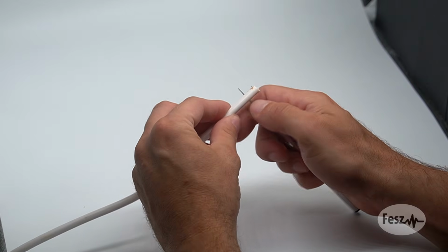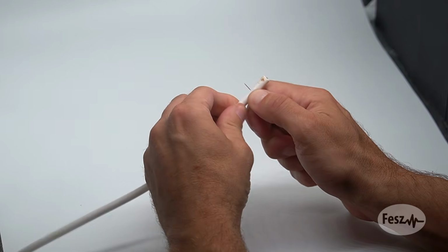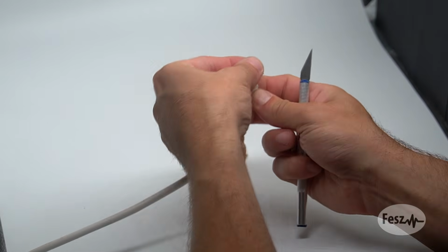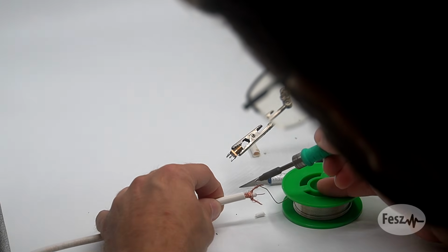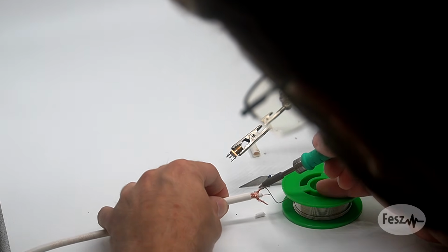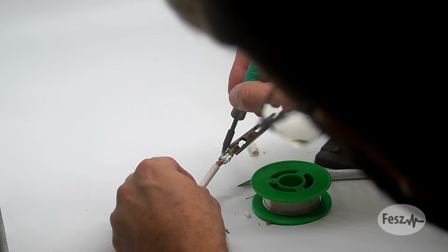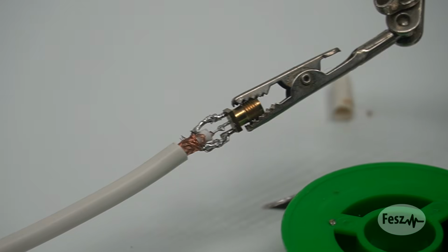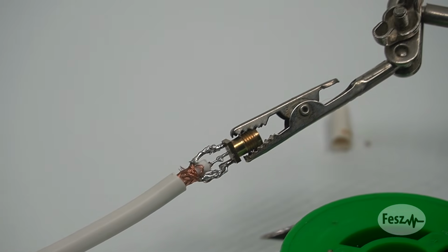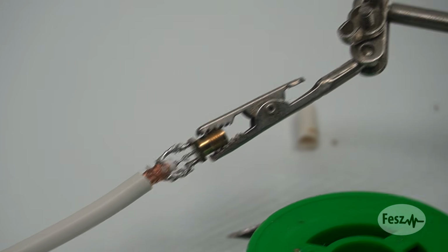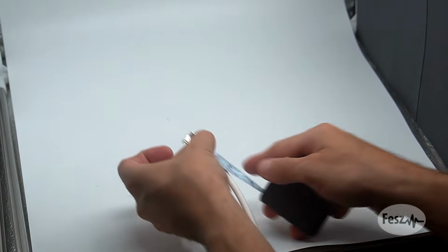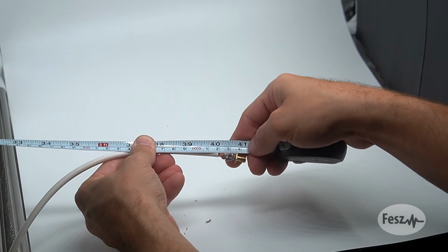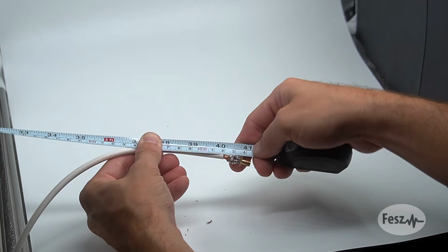So first things first, the cable needs to be connected to a test connector, and the exact cable length will then be measured. The longer it is, the less the exact connection point will matter. So this bit here with the connection has a different impedance and different propagation velocity. So you want this connection bit to be as short as possible to minimize the impact on the results. So anyway, the resulting structure I got is a 103.5 centimeter long piece of white coax cable.